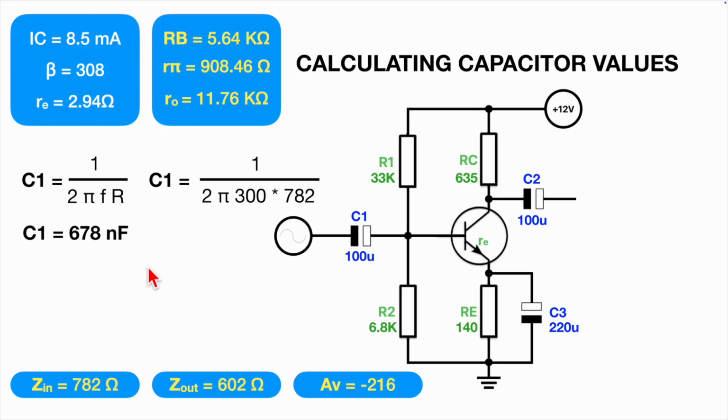I'm way over that. The reason I am way over that is because, bear in mind, this is functioning like really a 2-component RC filter, because all the impedance looks like one resistor basically in parallel with this series capacitor. So we're not talking brick wall filters here, people. It's a very gradual slope. So basically, the bigger you can get this, the more you're going to drive down that reactance at the frequency that you want. So that's why I've gone a bit kind of overkill as well.